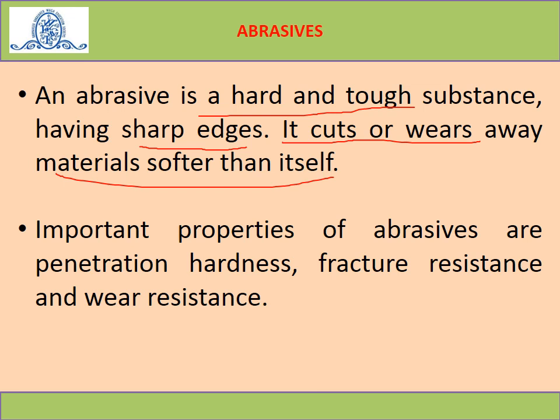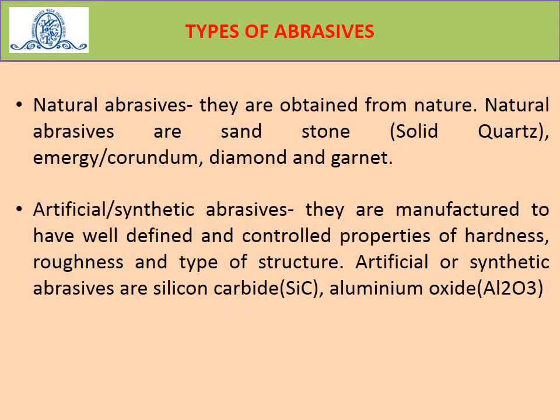Important properties of the abrasive. The abrasive particle should have penetration hardness, and it should have fracture resistance, so that no fracture takes place during machining. Then wear resistance, it should also have the wear resistance property, so that minimum wear takes place during machining.